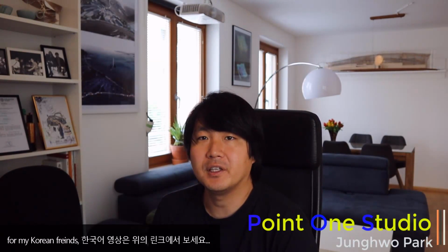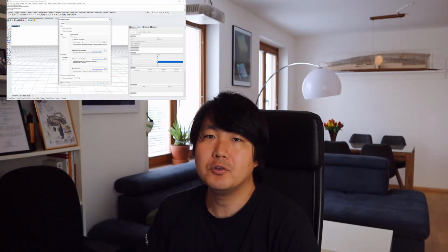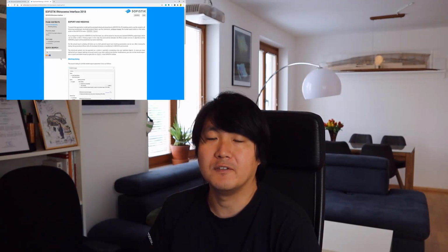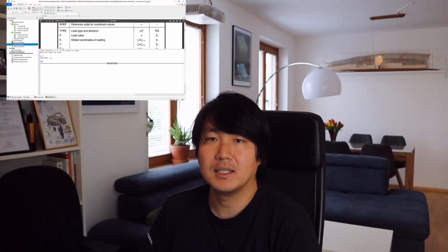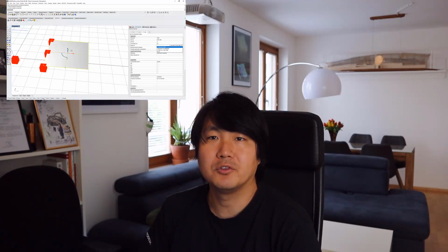Hello, today we're going to look at the Rhino interface for Sofistik. There are many workflows. We're going to make a geometry in Rhino, maybe simple framing with a cantilever beam, and also one simple plate that we can manipulate the geometry. And we'll use text input in order to define the loads in Sofistik, which sounds a bit complicated, but we'll go through baby steps on how we can define the text input.